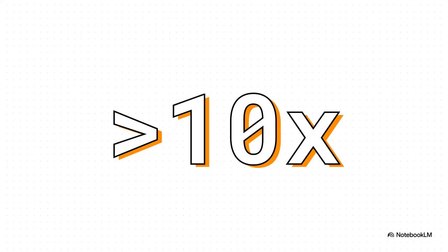And here's the payoff for all that work. Look at that improvement. The peak of that final pulse is now more than 10 times higher than any of the leftover noise. It's gone from a fuzzy, maybe that's a heartbeat, to an absolute, undeniable yes. Finding and counting the heartbeats now is a piece of cake for the machine.